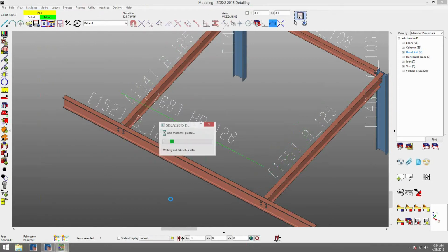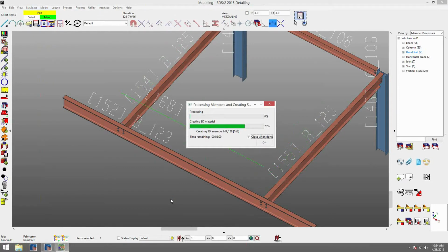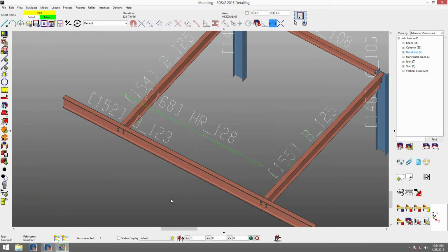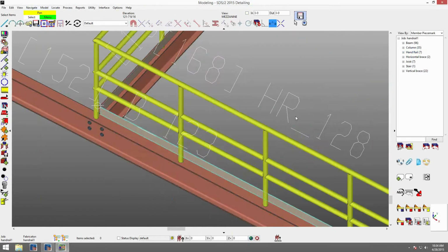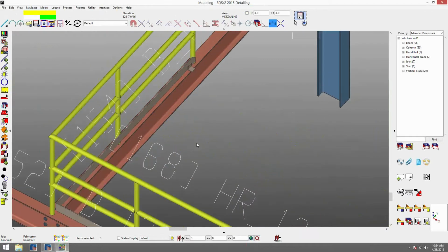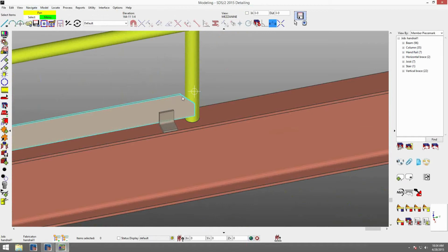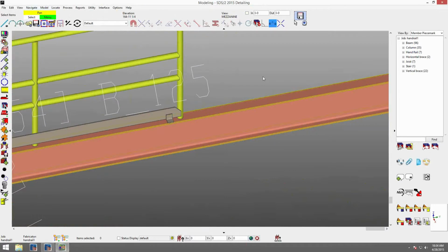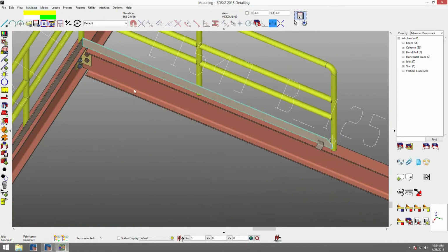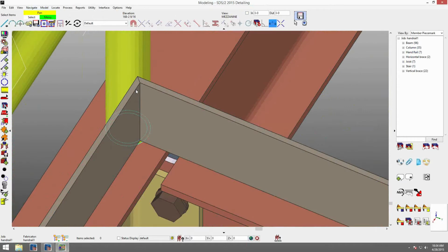and reprocess, we now have our toe plate. If I go over on this left end, for my left return, that's basing off of the left end there, it came down 2 inches and over 2 inches, and then I have my stabilizer angle, and that came over in the dimension that I set it to be. Now we will see here that our toe plate is mitered.